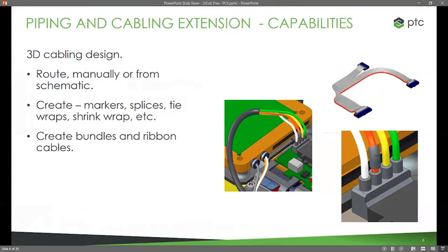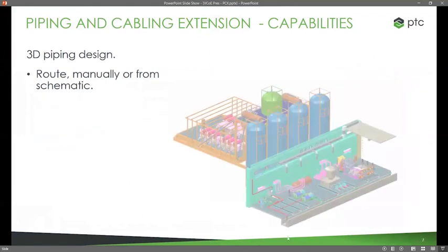There's going to be ribbon cables, giving myself a good visual representation, as well as having a very controlled bill of material at the end of this process. Individual harness drawings might be the goal of this, to be able to exactly link up what cable is going to be part of what harness.